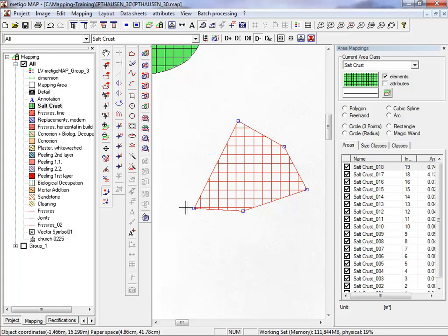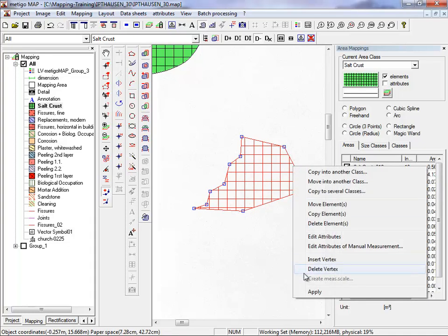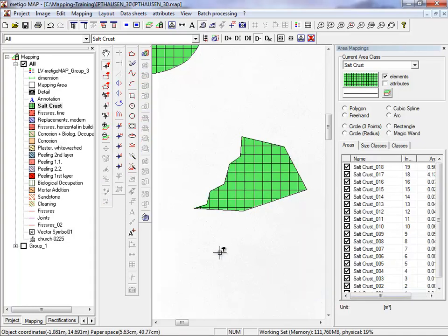We have to start at an already existing point, so we can choose one of our liking. Click once with left mouse click and draw our new outline. End the new line at an existing point with left mouse click. And choose now the polygon half that shall stay with the left mouse click. The other half is deleted automatically. Right mouse click and apply to save the changes.